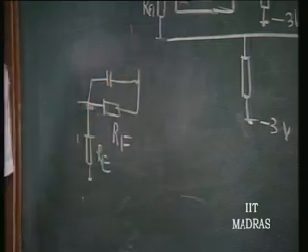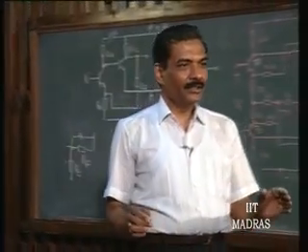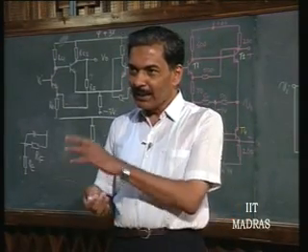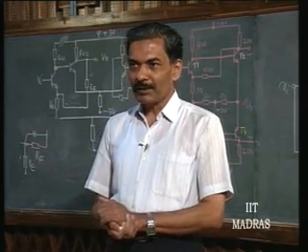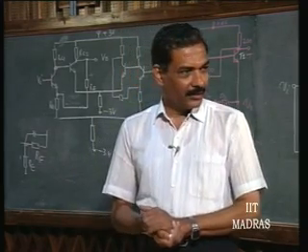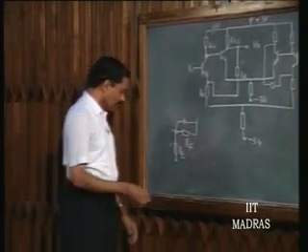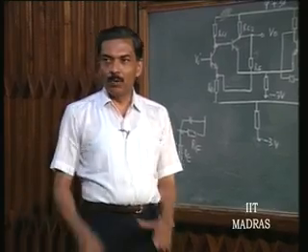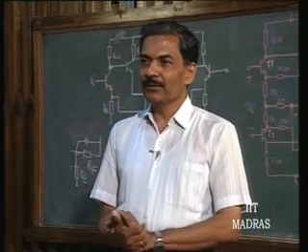This is something which you have been calling a speed up capacitor in the case of digital circuits. Okay. This will link the high frequency component very quickly with the feedback terminal. Okay. So, this is a lead lag compensation. This is going to result in a pole. Where will it result in a pole?